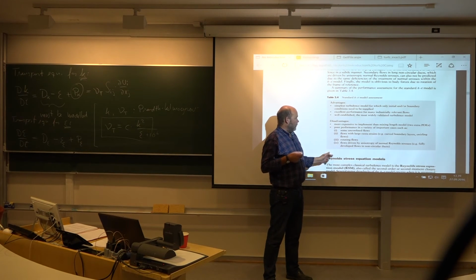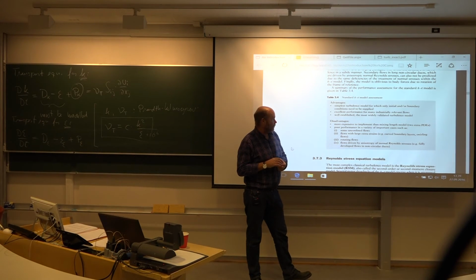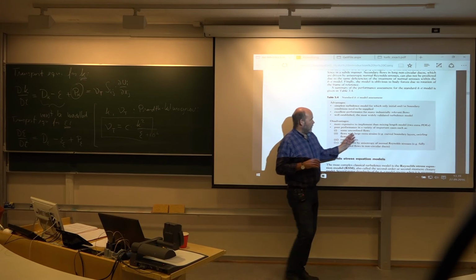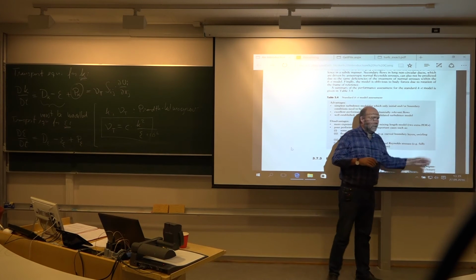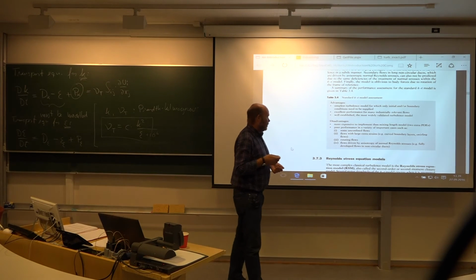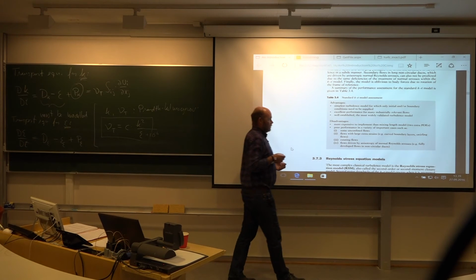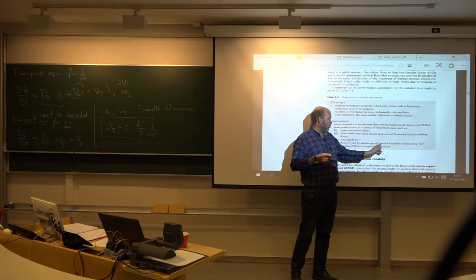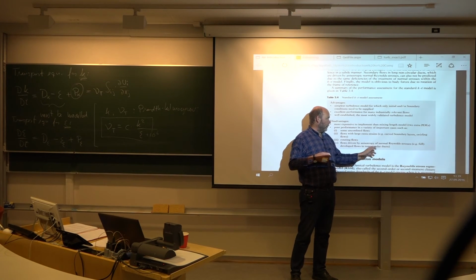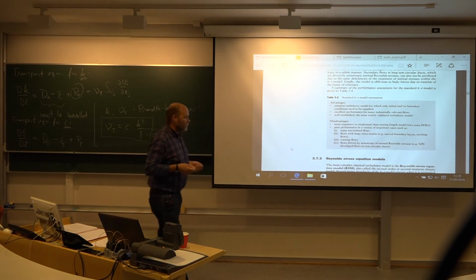We know it's quite poor for flows where you have, say, curved boundary layers, a lot of swirls, rotating flows, where you have strong influence of anisotropy of the Reynolds stresses, or say the turbulence quantities.